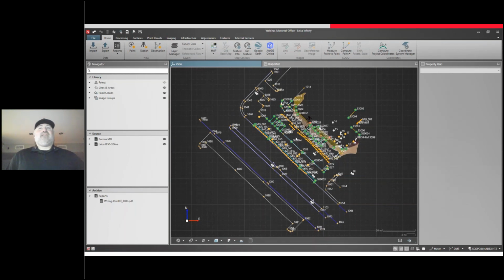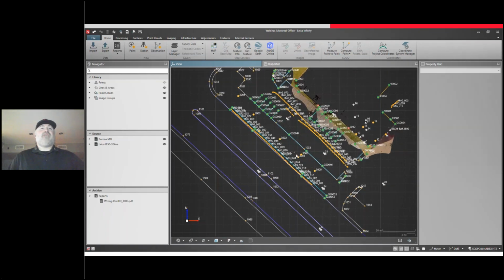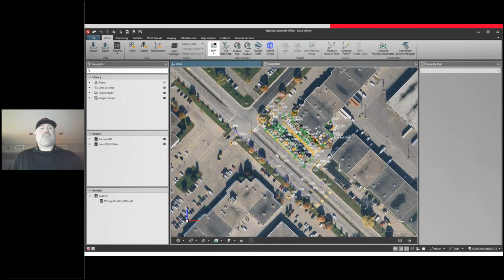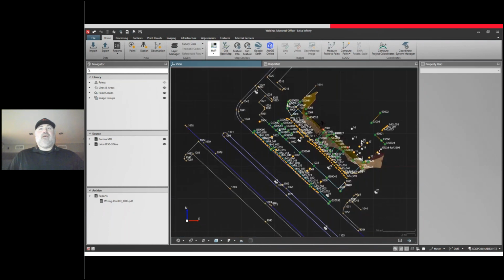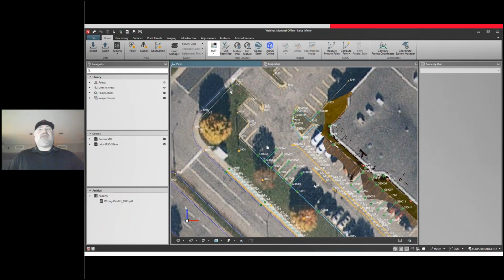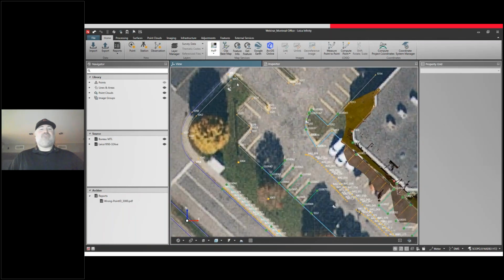So what stands out now is the line work created in the field and also the points that were measured. And again, this can be checked just visually, looking for crossing lines or lines not meeting. But as GNSS data is inherently georeferenced, it is possible to use the included background imagery to verify the line work. So here we'll turn on the Hexagon imaging program and the background imaging will stream. Zooming in, we'll see that there is a slight shift to the image due to the reference used, but it is still helpful in being able to determine if line work is missing or incorrect.